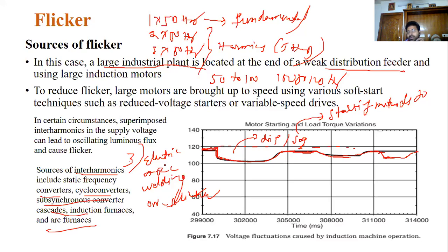Okay, suppose there is another problem. Suppose we have considered the three phases in our house. Out of three phases, only two phases are coming. That means one phase is open because of some problem in the power system. The remaining two phases are coming into the house. What will happen at that time? Some voltage fluctuations occur in the system.